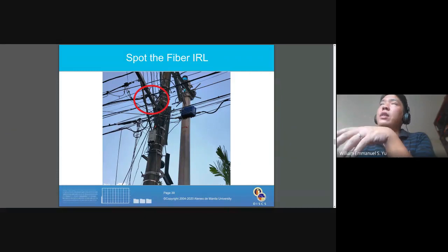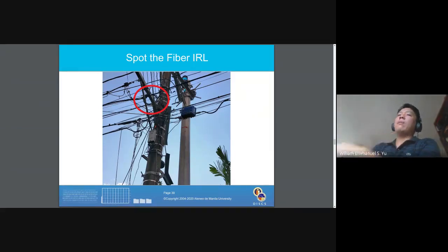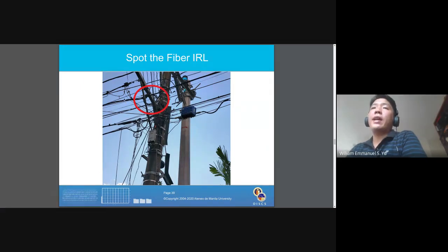If you stare at the post right now, you see these rings of wire. Have you ever wondered why they create these rings of wire? Parang sayang naman ng wire, hindi ba magastos yan? The reason why they create these rings is number one, it is more costly to cut a fiber optic cable, remove the ring, the extra wiring, and resplice it together. Mahirap gawin yan. Right? Because as I mentioned to you, brittle kind of fiber needs special equipment to connect.